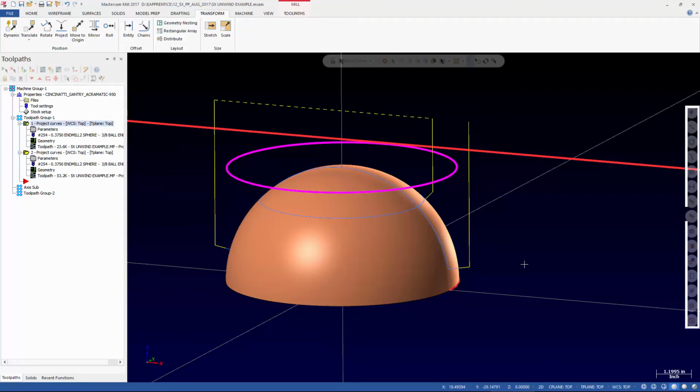So it'll actually analyze where your tool's at when it's in the material, and if you've got a half-inch move at 2 inches a minute, but it only contacts material for the last 100 thou, well, Vericut's going to do the first 300 thousandths at 150 inches a minute and then slow down. Complete is another one.